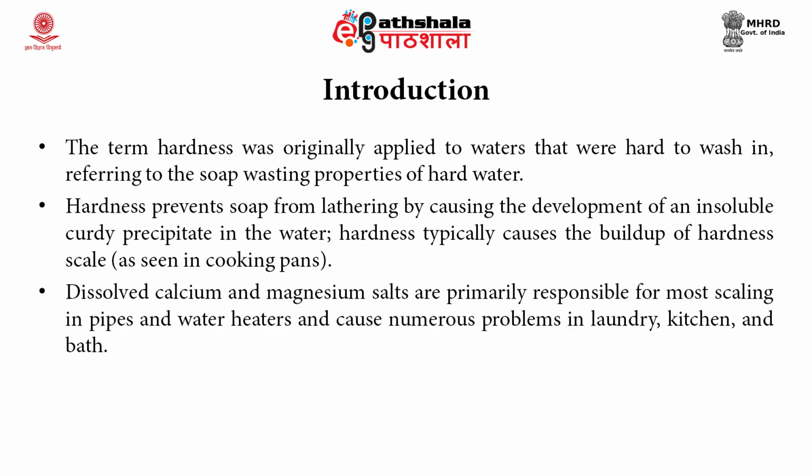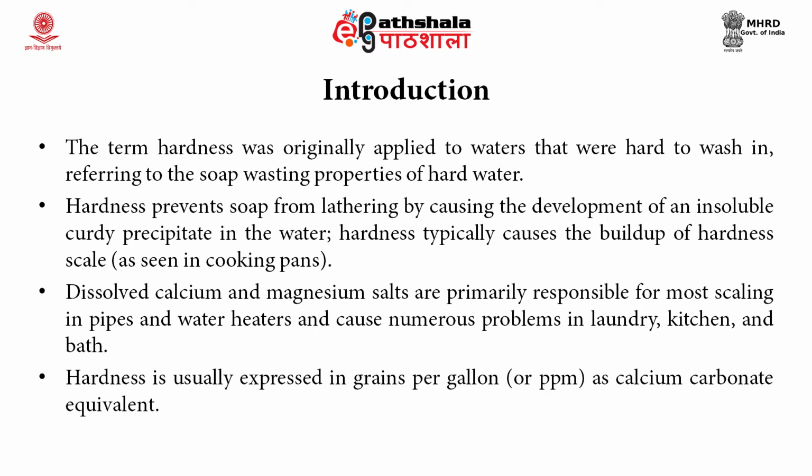The dissolved calcium and magnesium salts present in the water are primarily responsible for most of the scaling in the pipes and water heaters, and cause numerous problems in the laundry, kitchen and bath. The hardness is usually expressed in grains per gallon or parts per million as calcium carbonate equivalent.